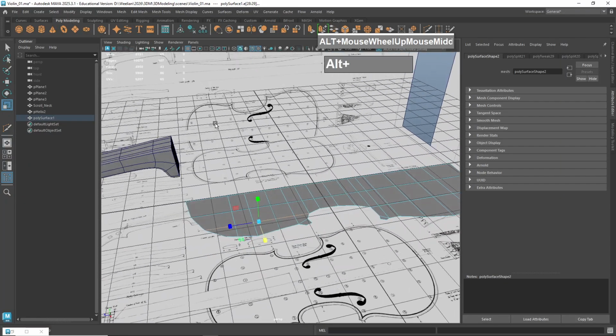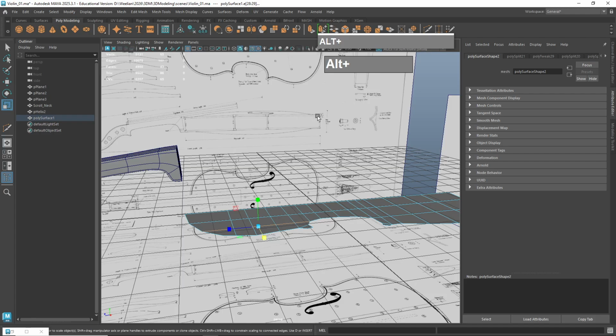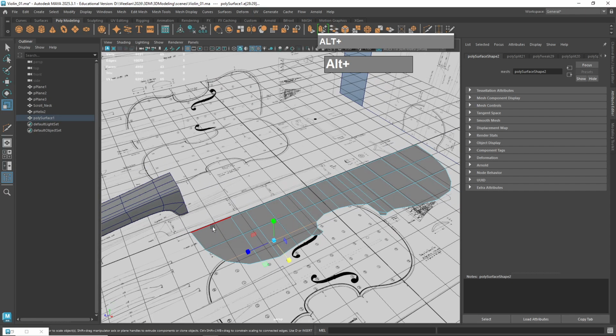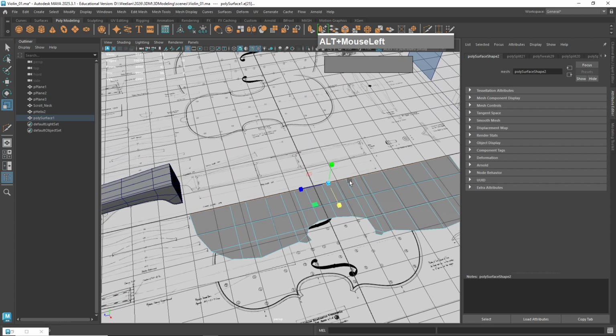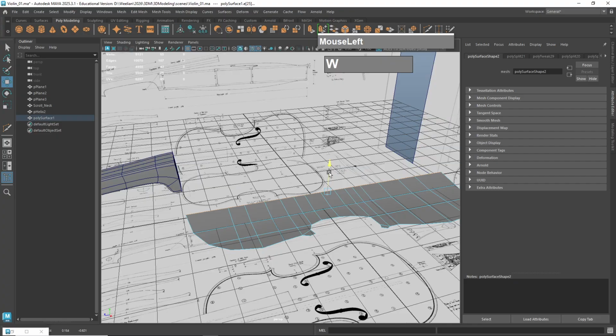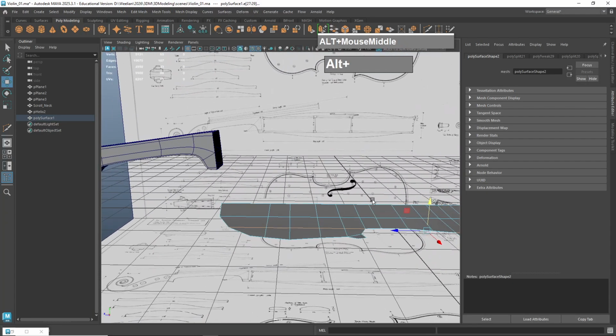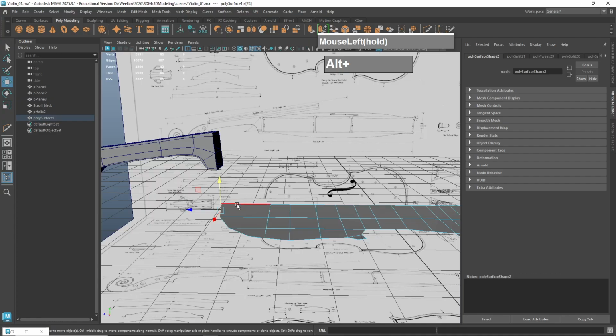that we can start to bulge out. So if you look at the violin, right, it actually bulges out in this section over here. So the center line, okay, let me just grab the center line here and just move it up slightly. Click to just move this up. See the center portion here, I'm going to use the vertex to just push this down.